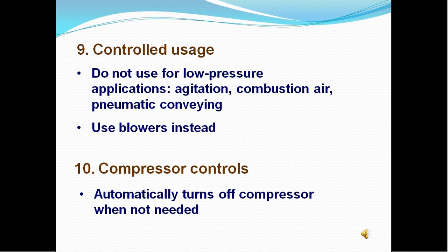Compressor controls. Air compressors become inefficient when they are operated at significantly below their rated CFM output. To avoid running extra air compressors when they are not needed, a controller can be installed to automatically turn compressors on and off, based on demand. Also, if the pressure of the compressed air system is kept as low as possible, efficiency improves and air leaks are reduced.